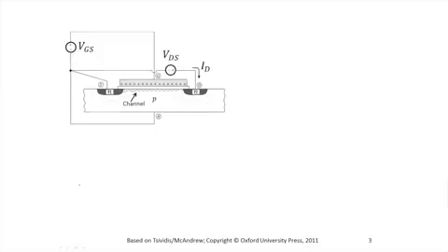So now here you see the MOS transistor biased in a common way. We have shorted the body or substrate to the source, as you see here. And then between the drain and the source, we apply a positive potential, positive voltage VDS, drain source voltage. And to the gate, we apply a positive potential with respect to the source, VGS.